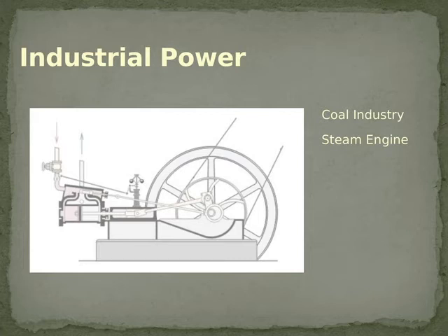A piston is just this plunger-like thing that is moved by the steam engine. It just goes back and forth. But you want to turn this linear motion into rotary motion. It'll have much more application, so you add a crank to it. His engine was also more efficient, and so now people had a way of creating rotary motion. So, if you're thinking ahead here, you may say, aha, rotary motion. What can we do with rotary motion?